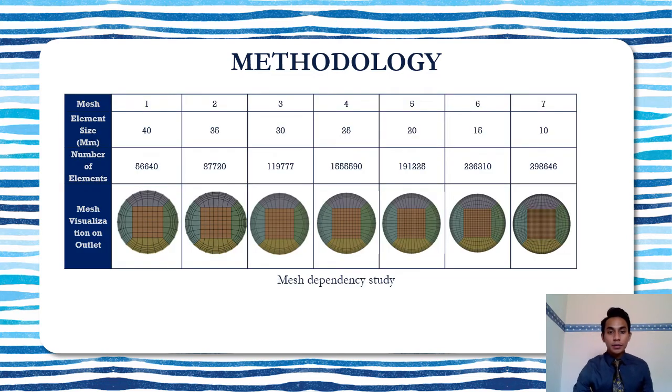This is our mesh dependency study. So we collect the data by using the parameter function. This table details out the parameters of mesh of different refinements. The maximum pressure was quantified from 7 different element sizes, and slight differences were produced from mesh to mesh as presented.